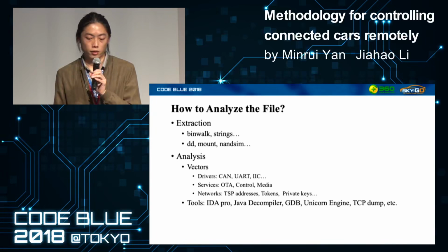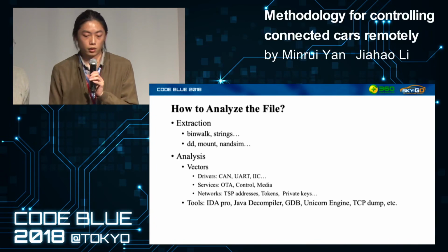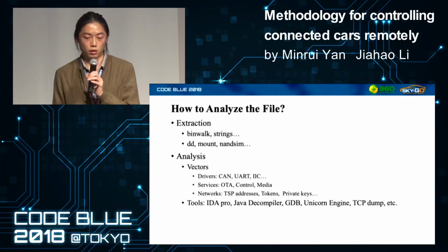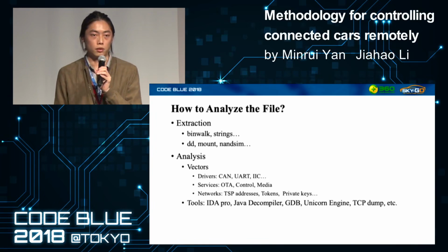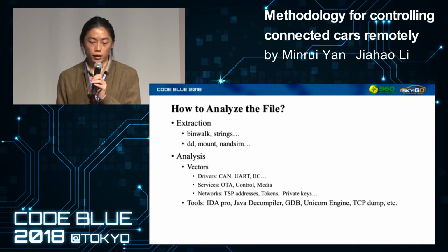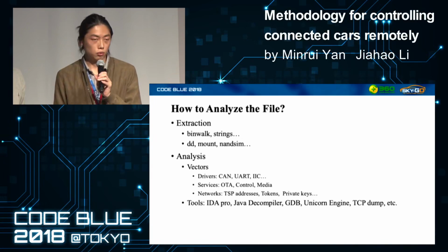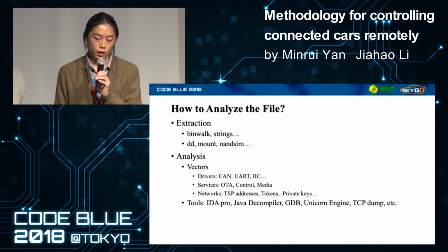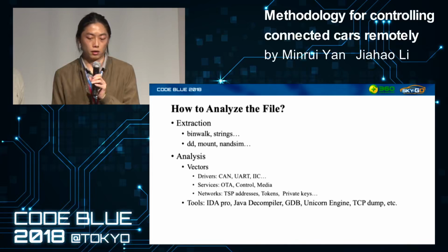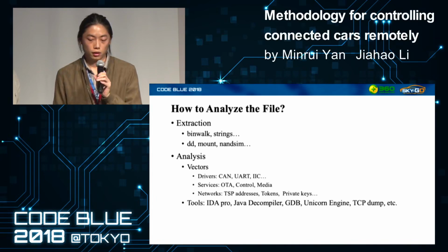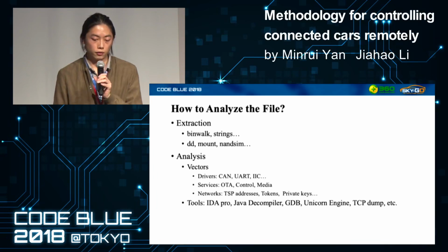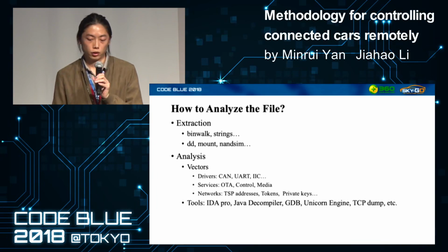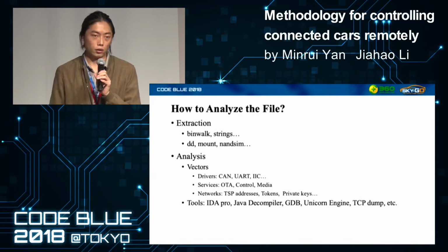Then you can reverse engineer programs or bootloaders with these common tools. You may ask, how do you know which to analyze? If you know about embedded development, you must know the system driver is the key. So we can analyze the program to see how it drives the MCU. By the way, we can find the TSP configurations and use a TSP dump to capture data. If the data is encrypted, you can reverse the cipher algorithm.